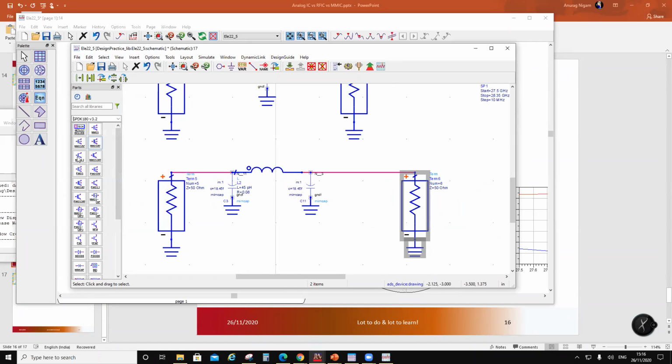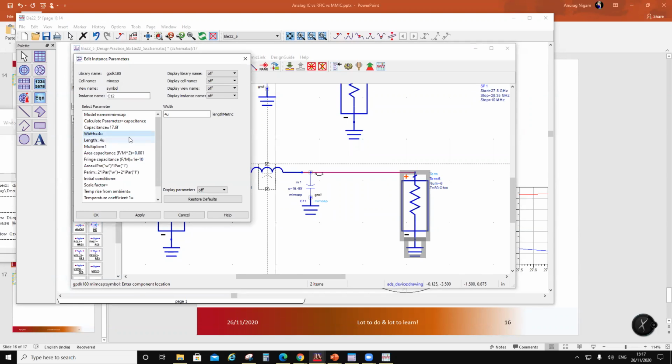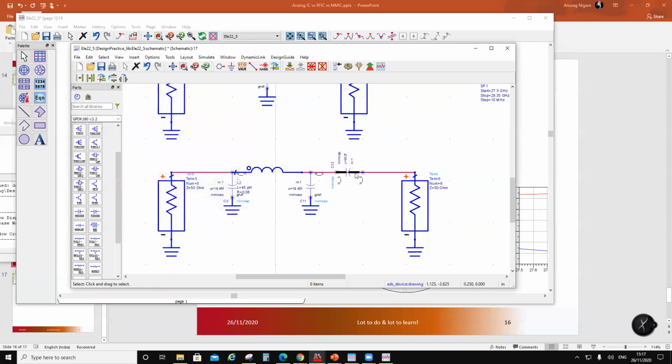So, large capacitor, MIM cap, and I want a large cap. So it's just like a coupling cap, 30 and 30, right? And rotate here. So this is more like a band pass match, right? This is like a band pass. Okay, and let's make a big coupling cap here. Done. Let's see how bad is bad.